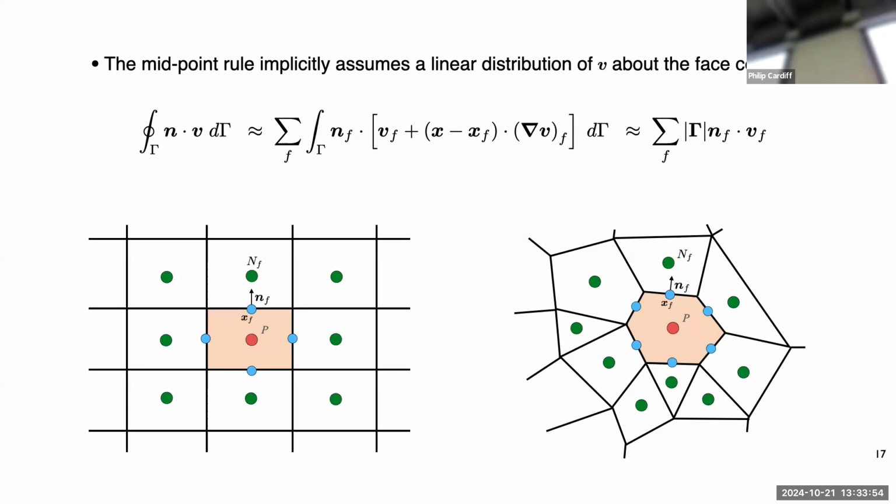This is why the finite volume method can apply to any general grids, because nowhere here are we referring to a specific shape. We don't need specific shape functions for particular elements. We're just summing over faces, so it doesn't matter if there are 6 faces or 4 faces or 5 faces, or in 3D you could have 25 faces or something like that. You could have a football-shaped cell. You can just sum over all those faces.